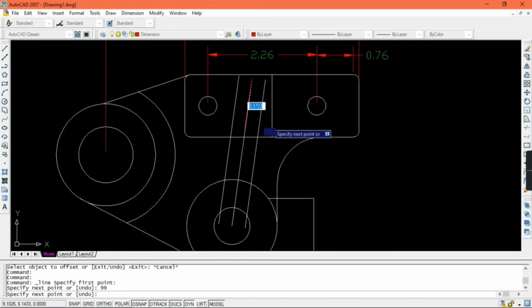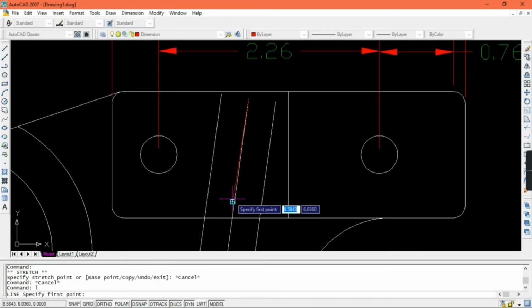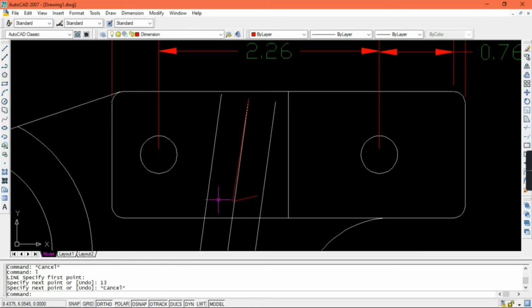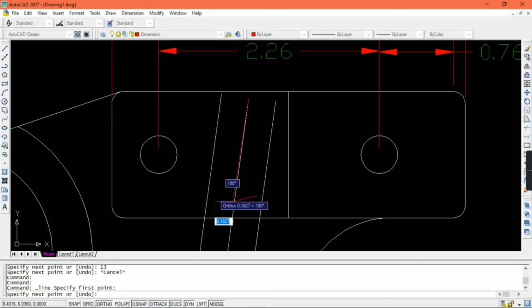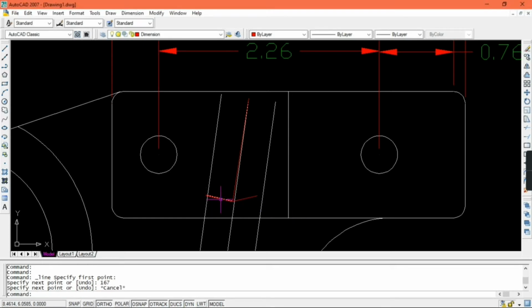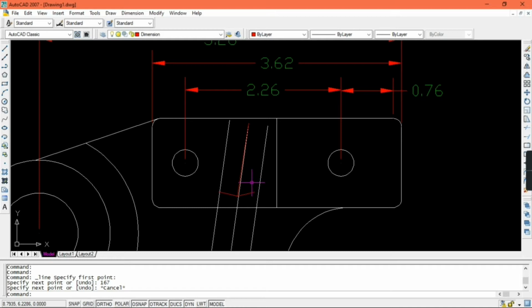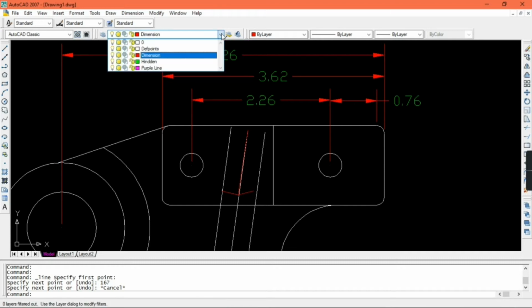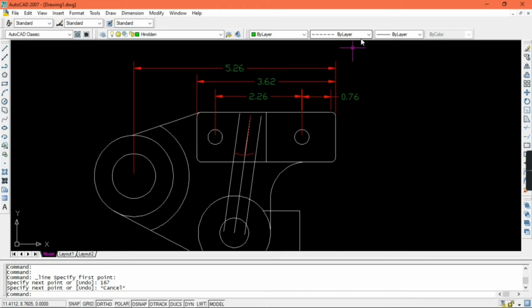Then drag the line to the right 0.28 distance tab 13 degrees. After that, starting from the center to the left, distance of 0.28, then an angle of 167 degrees. After doing that red line, you can now click the layers, then choose hidden, change the line to a hidden,